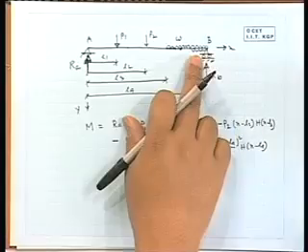So, moment is minus EI d2y dx square, we will get two constants. So, two boundary conditions are necessary, and these boundary conditions will be in the form of deflection and slope, right. So, if it is a cantilever problem, at one point we are getting the condition deflection as well as slope are 0 at the fixed end, but in the simply supported case slope is an unknown quantity here. So, slope we can't utilize, we can only take the help of deflection at A and B, means at the two supported points.